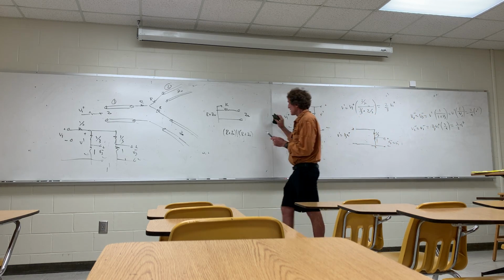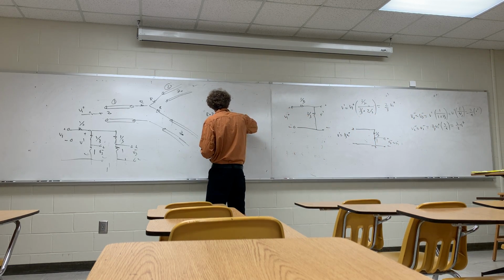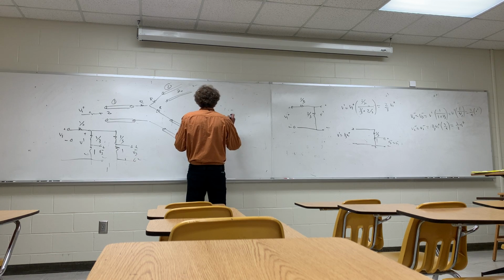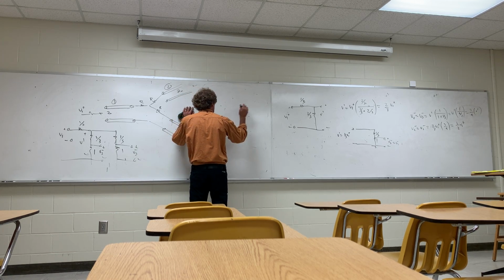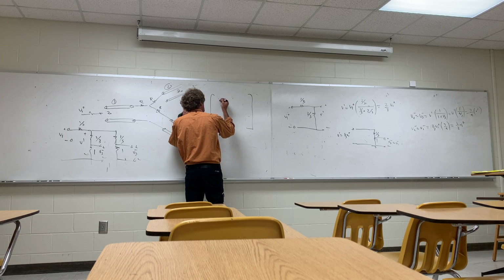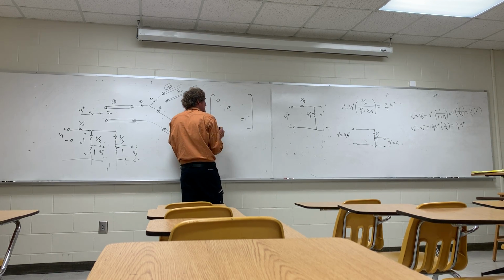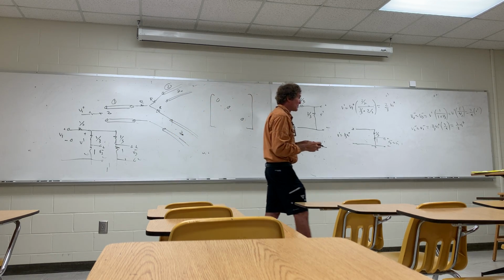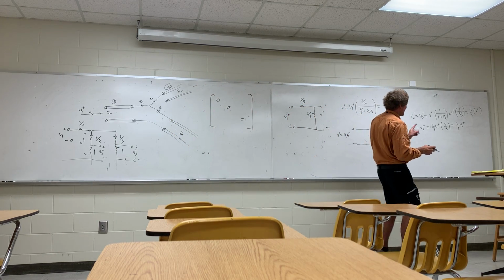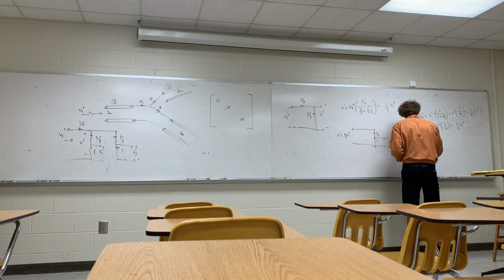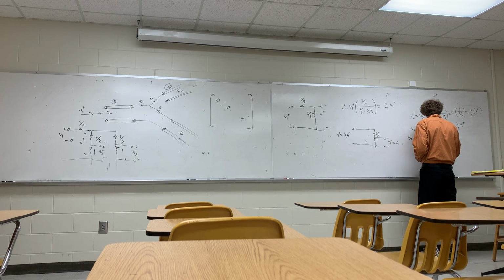So when we think about S parameters, this is going to be a 3-port, so S11, S22, S33 for this one are all 0. Then the next one I get, when I look at this, S21, which will be equal to S31, are really equal to V2 minus over V1 plus, or V3 minus over V1 plus.